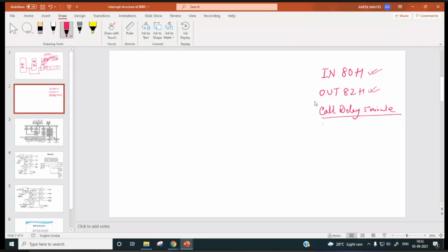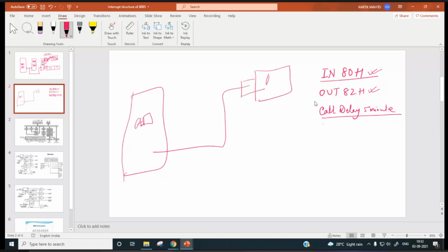So in port A0H, that time someone said that from port A0H data will come into the accumulator. I said that in port A0H we have connected an ADC, and the ADC is digitizing the temperature sensor data. Then how much is the temperature? For displaying, we send it to port 82H, where the display is connected, so 25 will be displayed over here.